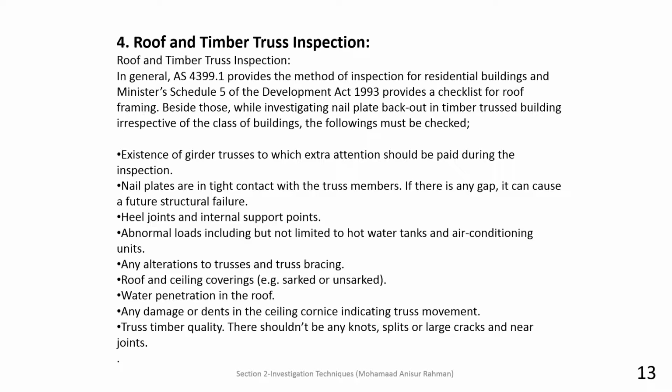Nail plates must be in tight contact with the truss members. If there is any gap, it can cause a future structural failure. Heel joints and internal support points must be checked. Any alteration to trusses and truss bracing must be checked. Whether there is any water penetration in the roof, any damage or dents in the ceiling cornice indicating truss movement.